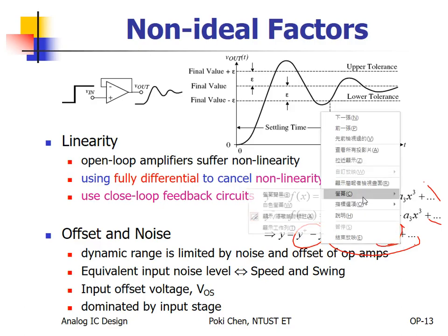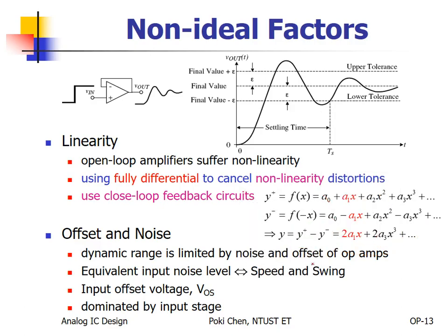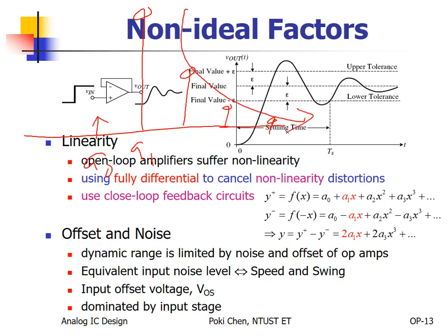For real applications, look at the spectrum. Offset here, that is A0. Then A1, the one you would like to have. And then A2, A3, A4. Usually it degrades very soon, from the fundamental to the second harmonic, third harmonic, all the way, decaying very soon.